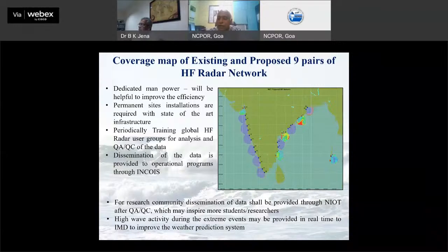It is 6 kilometers from the coastline for this long range data. Because the first grid is 6 kilometers, that 6 kilometer grid has some problems due to the coastal effects. But when you use the high resolution, like 25 megahertz, we can go even to 200 meters from the coast. And if you have a 45 megahertz system, you can have current data from 75 meters from the coast.